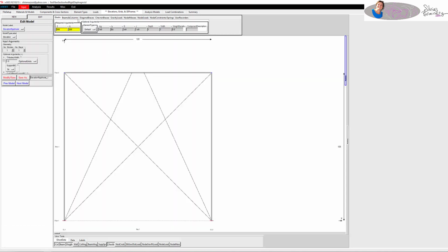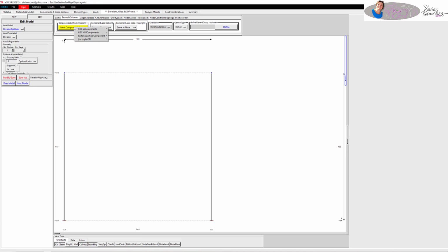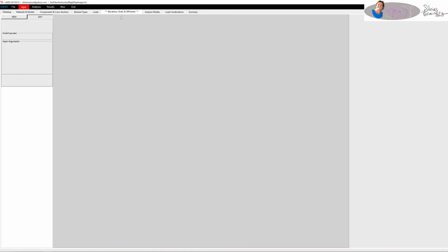Then what I'm going to do is remove the beam and replace it with one that has the free axial. So this has got the uncoupled, only for the beam, right? Because you only care about the beam element having no PM interaction. So there it is, and I just save it under a new name.